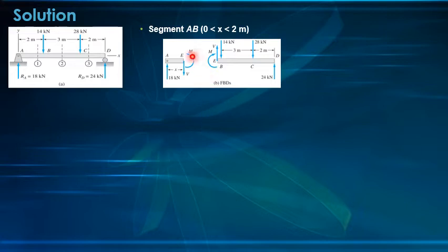So, since pinutol natin tong part na to, from A to the cutting plane, that will be our X. And there will be a shear force at that cutting plane and a moment. We're going to analyze the whole system, class. If we're going to analyze the whole system, magkakaroon ng bending like this. So, there will be a positive shear and a positive moment. Diba sabi natin ilalagay yung positive dito sa positive tong shear at saka tong moment.